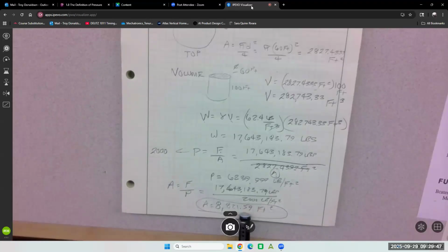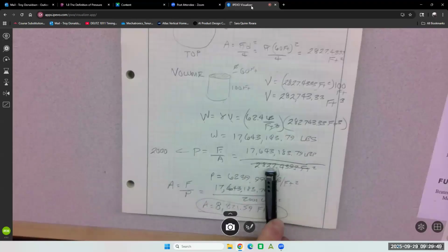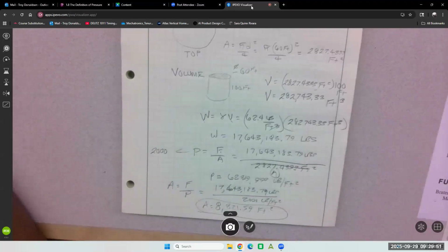About 3 times the amount that we had before. And that should keep it from falling into the ground, right? Sinking. And we can go right to the soil pressures. There's no factor of safety there. We can use it right to those pressures.